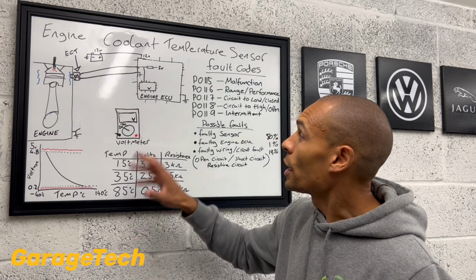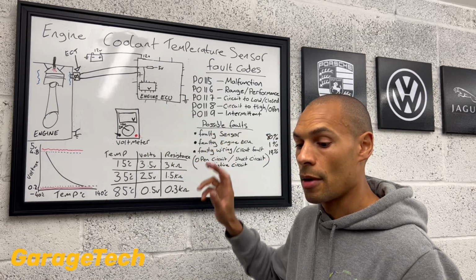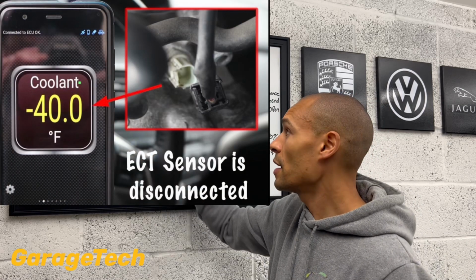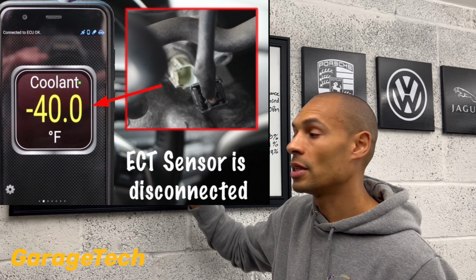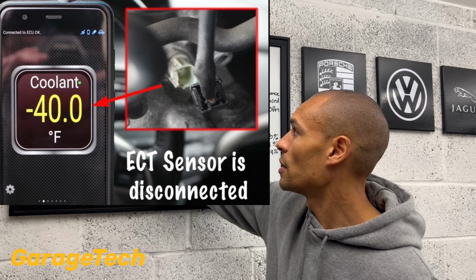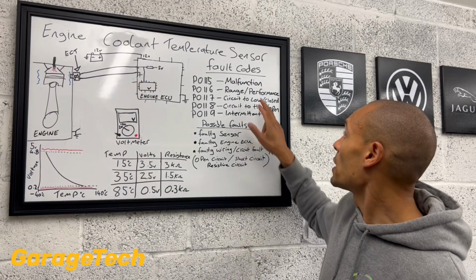Another thing to check and look for as well, if you have got some sort of diagnostic tool where you're checking your fault codes, if you can check your measured value blocks, if you can unplug the sensor and then check what the temperature reading is whilst it's unplugged, it should be minus 40 degrees. Okay, so that will give you an indication that part of the wiring should be working correctly. So that's looking at that range performance.